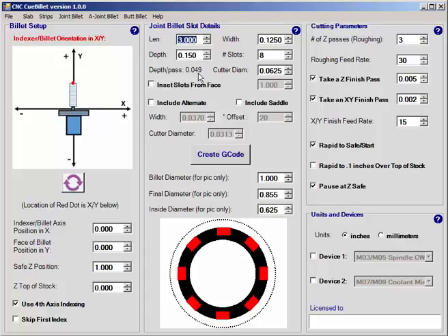Now let's look at the slot details. Our imaginary strips were machined to be 2.4 inches long. I will set the slot to just slightly longer than that. The width is already set to 0.125, but that may need slight adjustment. Let's pretend our strips were exactly 0.125. We might initially set the slot widths to 0.126 and then do a test fit.